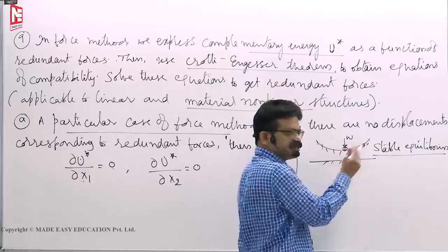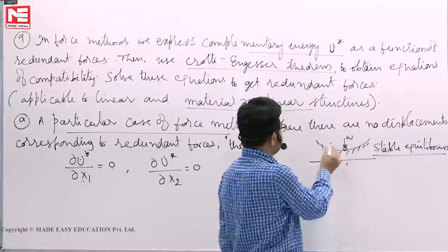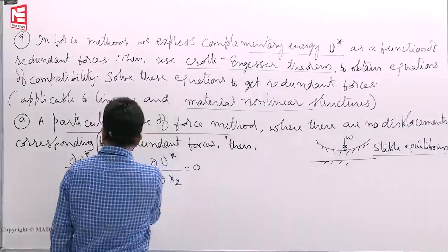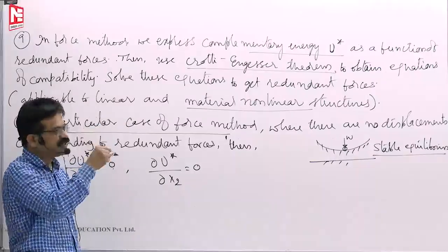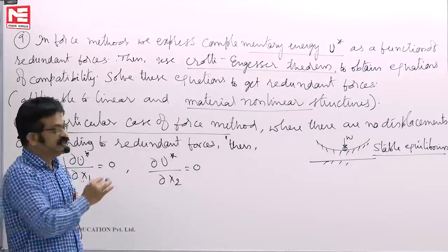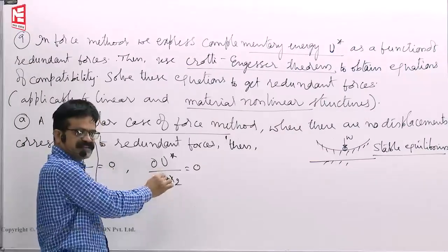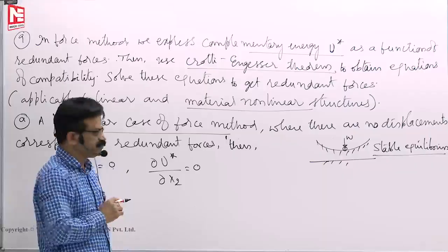Energy stored now in this one is the minimum energy level. That means here the first derivative, dou U by dou x, is equal to 0, which implies that the complementary energy in this case will be a minimum value. This represents the principle of minimum complementary energy.